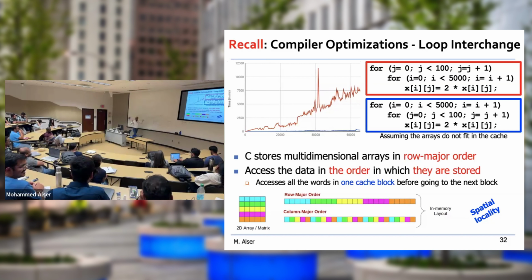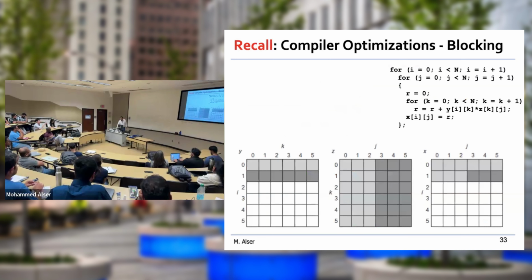But once all your data is in the same row, then you access that row, you keep it in the row buffer and keep switching between columns. And that's much faster than closing the row, accessing another row, and moving on. We'll discuss it for caches.